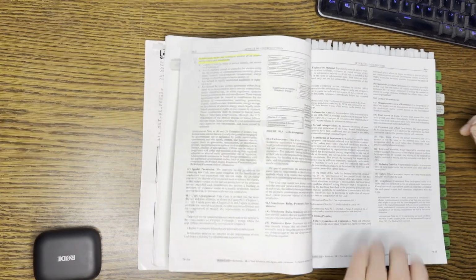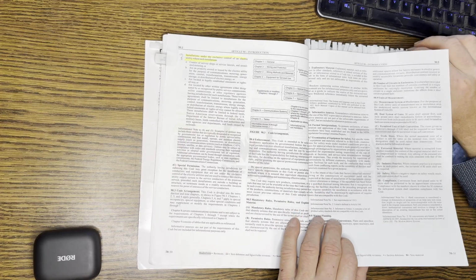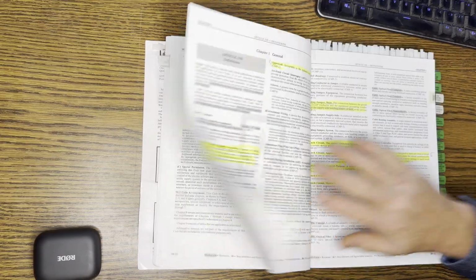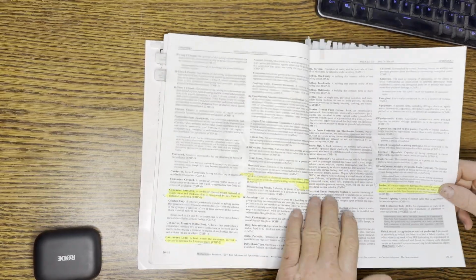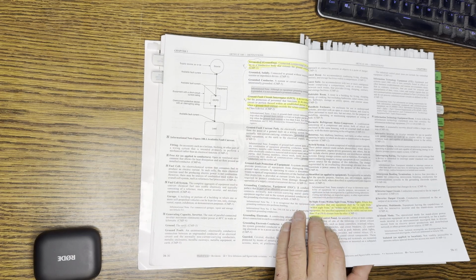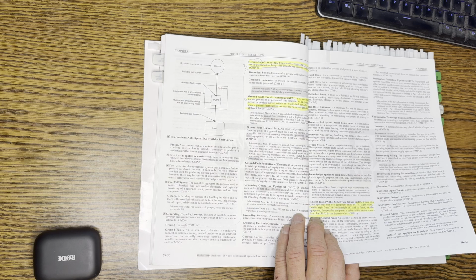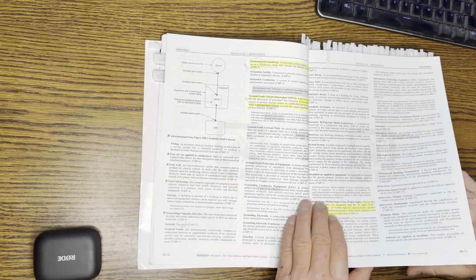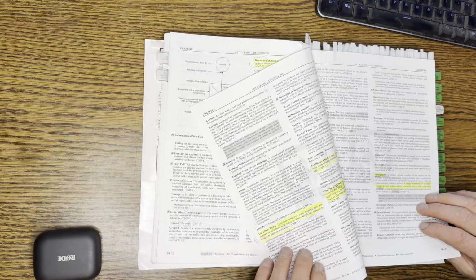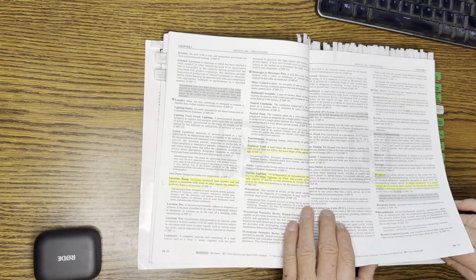Obviously not applied. That particular section, section 90, exempts the NEC from power generation plants. Go through the definitions. There's actually a few things like a service, grounding electrode conductor versus grounding electrode. Know that. A feeder versus a branch line versus a service line. Basically go through and know that.